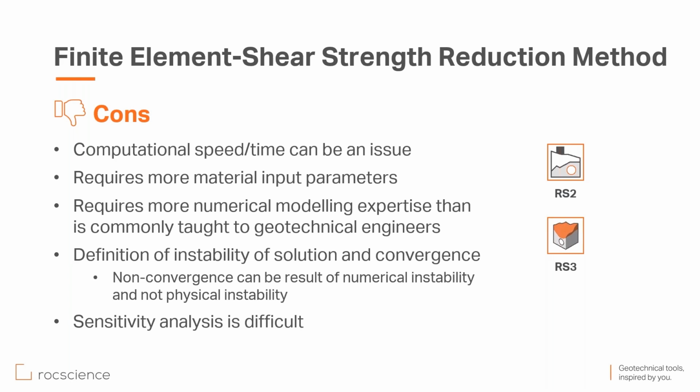But sometimes non-convergence can be the result of numerical instabilities rather than physical instability. And since the solution provided by finite element SSR is rather time-consuming compared to limit equilibrium, sensitivity analysis and probabilistic analysis are rather difficult using this method.